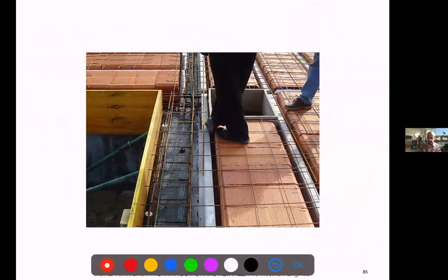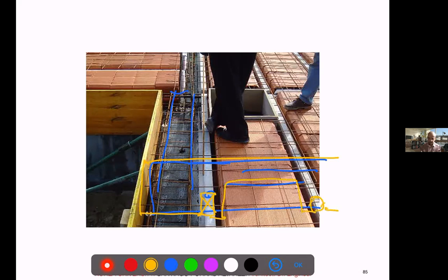This is how this is done. This is just a reminder to see how it works. So these are the prefabricated ribs, the metal mesh, and these are like side beams just to complete the strength of the slab. If we make the section, we'll have one beam, a prefabricated rib, the form, another rib, and then concrete will be filling inside.